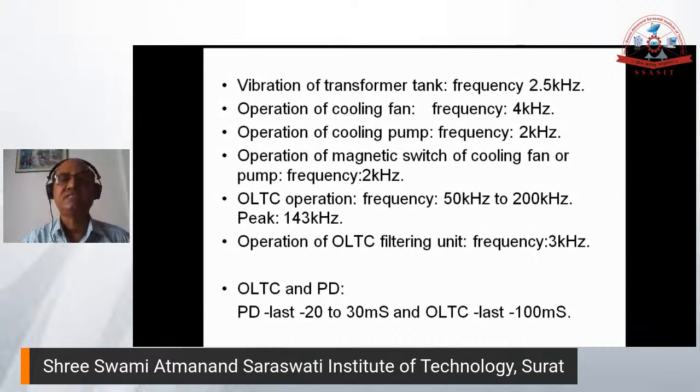PD and OLTC operation seem to be in the same zone, but that is separated with a time analysis. OLTC operation pulses will have a little bit wider duration, 100 milliseconds, whereas PD will have 20 to 30 milliseconds. So that can be identified.